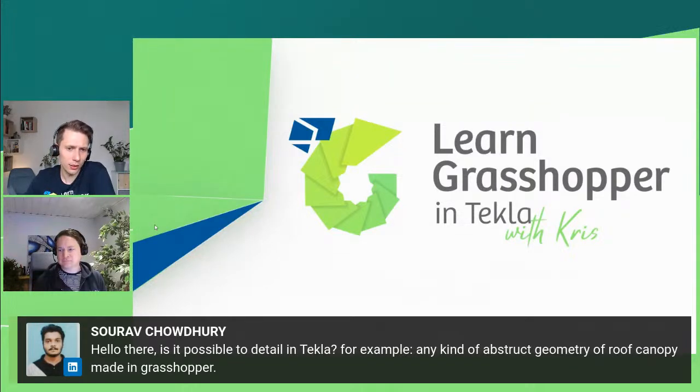Is there a possibility to detail in Tekla any kind of abstract geometry, for example a roof canopy made in Grasshopper? Of course you can make all the abstract shapes. Of course you have some limitation, because Tekla models with polylines and polygons, so you will not get all these amazing curves, but you can get a really good approximation. You can also place the connections, and that might become really easy with Grasshopper and reacts to any changes you have. There was a basic example in the last webinar about placing connections on a warehouse, if you want to see how that might work. It's the same even if the geometry is more complex.